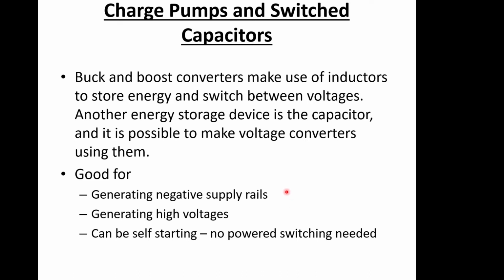We can boost the voltage as well, but we have a choice of techniques. We can either use the inductive regulators to boost voltage, or we can use the capacitance one as well, but capacitance ones tend to be a bit limited on the amount of current they can supply, but they're good at generating very high voltages. And they can be self-starting, which is useful in certain areas.